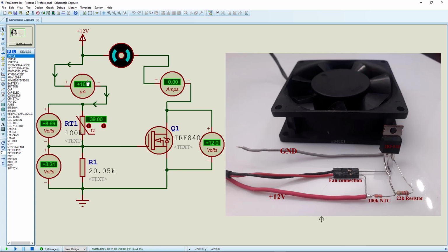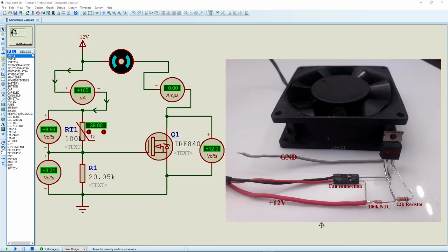As you can see, that means the threshold voltage is also increasing. And you can see clearly that the current is also increasing, because the total series resistance here is decreasing, so you'll have more current flowing through that series circuit. These are basic principles of electronics. Okay, so please guys, you have to pay attention. So in a nutshell, the voltage across the thermistor is your V supply minus the voltage drop across R1, which is your V threshold.